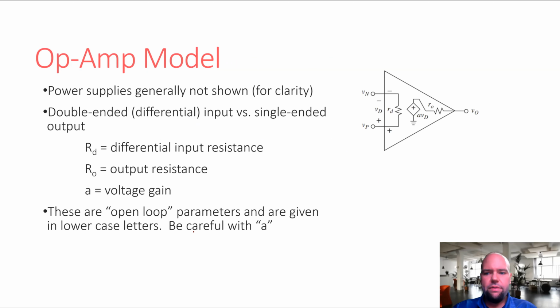So let's consider the op-amp model. An op-amp model is a special type of two-terminal amplifier. The only real difference between the op-amp model and the generic voltage amplifier model that we just showed is that the gain term should be very high for an op-amp. A normal amplifier's gain could be 1, 2, 3, up to 10. The idea behind an op-amp is that it's a voltage amplifier with a very high gain. Very high, not really clearly defined. And you'll see in this class, they sort of work even when the gain is not very high, just not great.